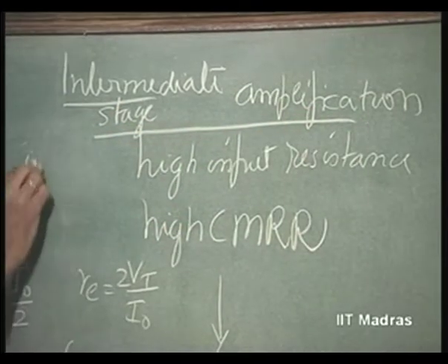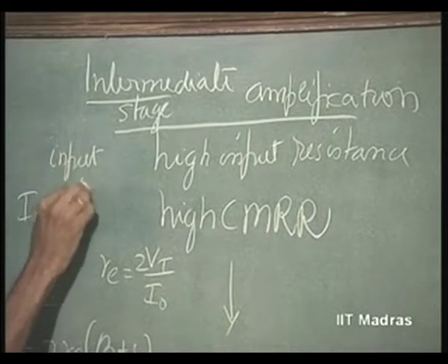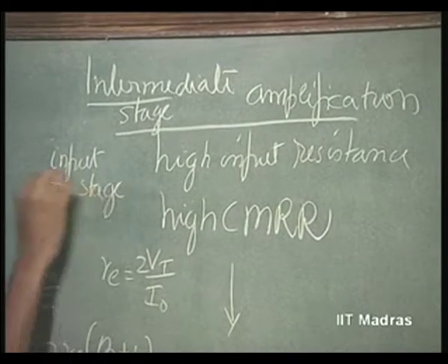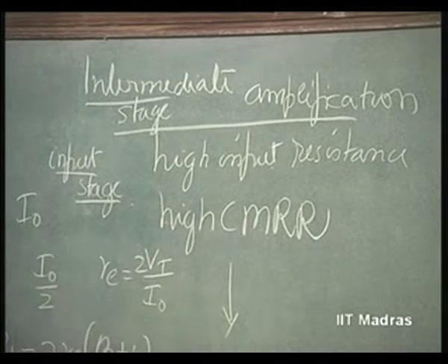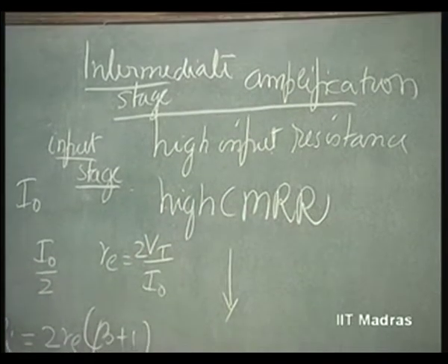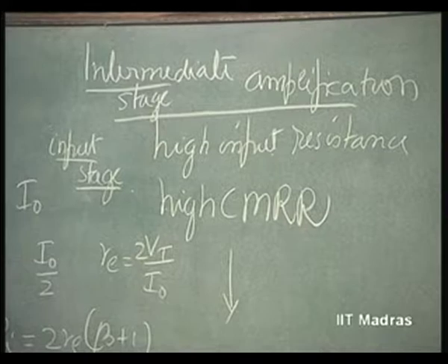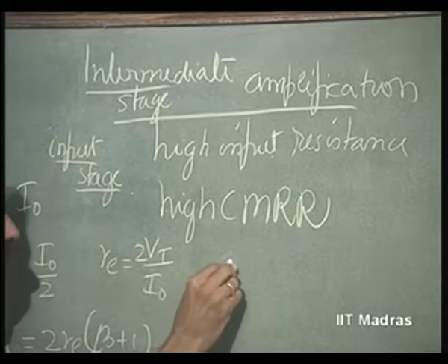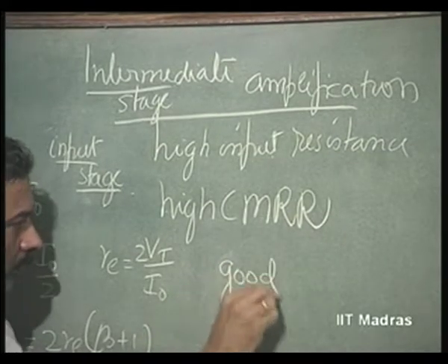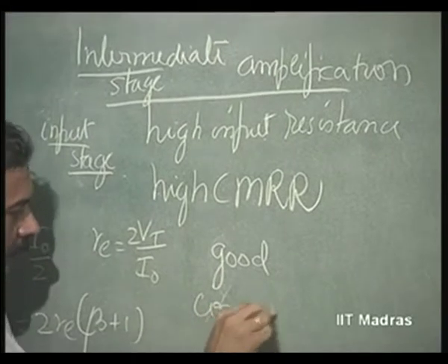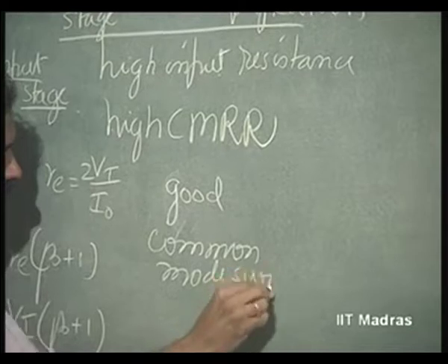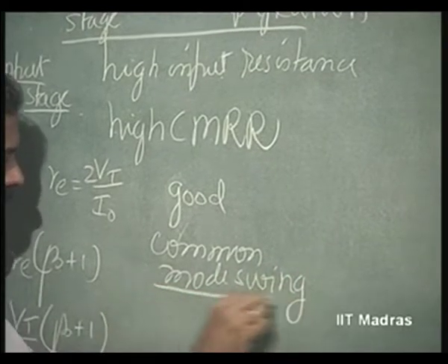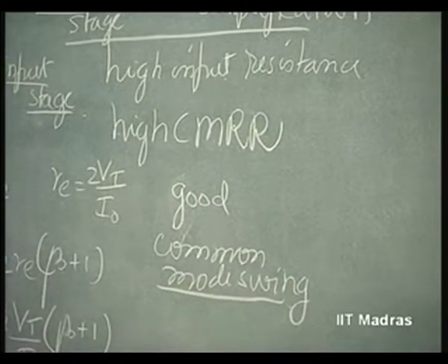Whereas the input stage's major responsibility is high input resistance, high CMRR and good common mode swing. This I have told you once again.